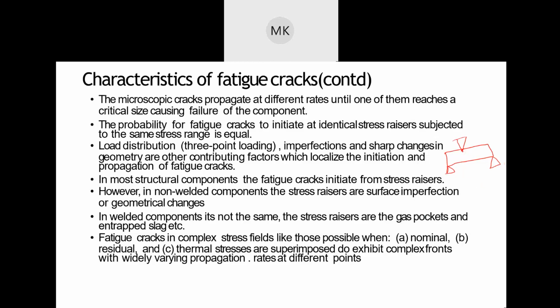The reason why the crack growth is controlled is because you have two types of loading that is happening. The bottom part of the material is undergoing tensile loading, while the top part is undergoing compression loading. So there's two types of loading happening which is canceling each other, but you know that the cracking is going to start because of the way it is.